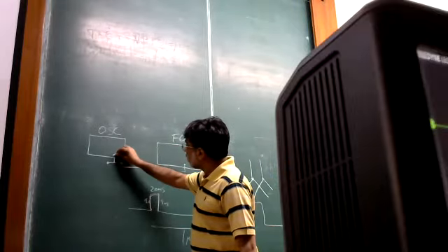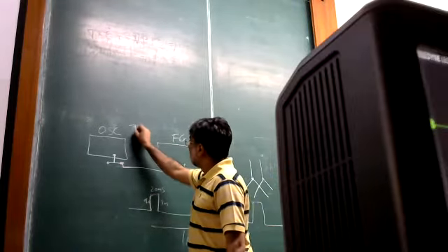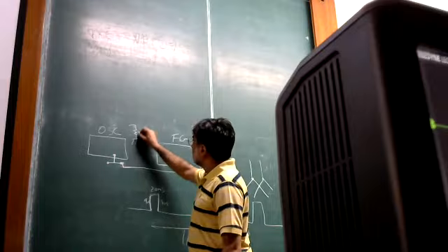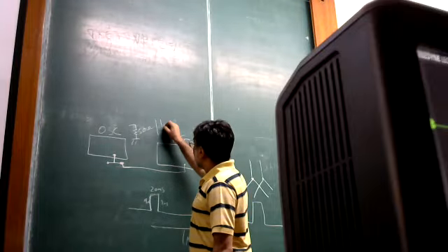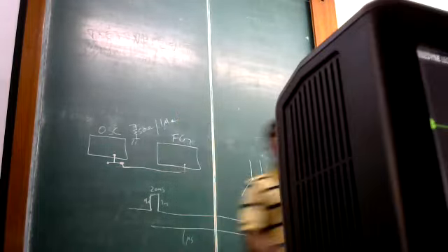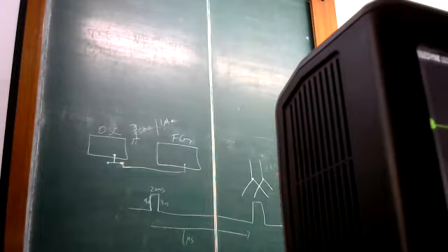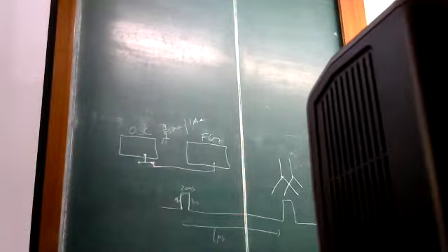So I can actually choose the oscilloscope to either have 50 ohms to ground or 1 mega ohm to ground. I'm sure many of you must have played with oscilloscopes, and these settings exist in some of them. Right now it's connected to the 1 mega ohm setting, and that's the reason why the voltage is going from 0 to 2 volts, even though I have set 1 volt peak to peak amplitude here.